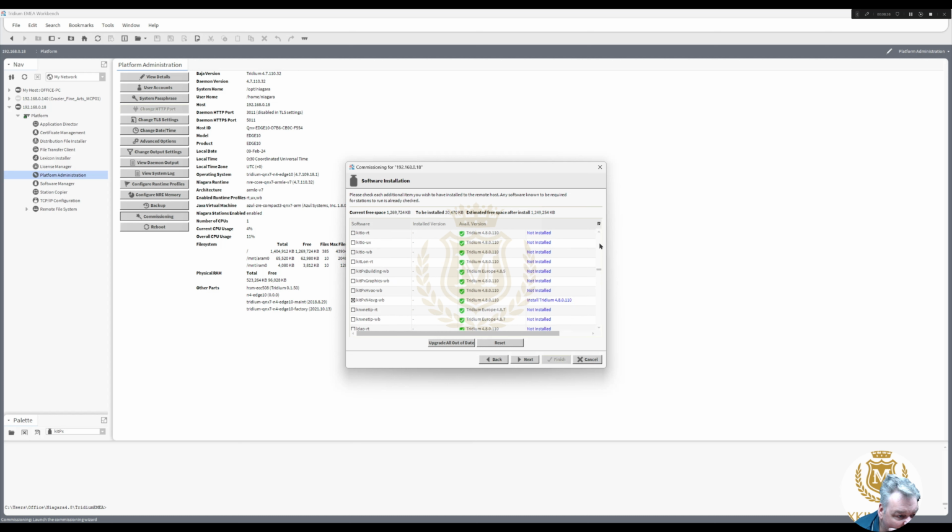Where are you, kitControl? Has it actually already been installed? Yep, they're already installing it. kitControl. So that's fine then. And they're already installing Modbus. Just curious now whether they're installing BACnet. Yeah, it's installing BACnet as well.